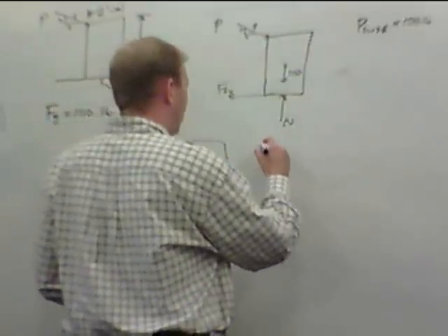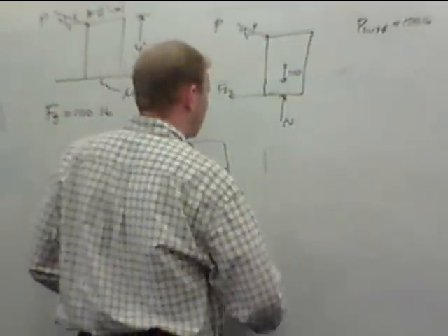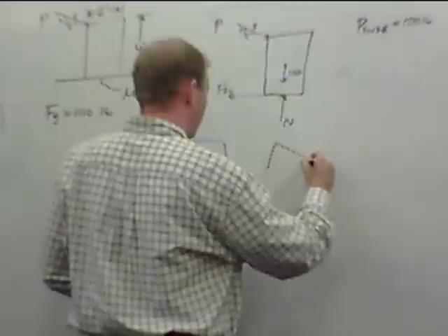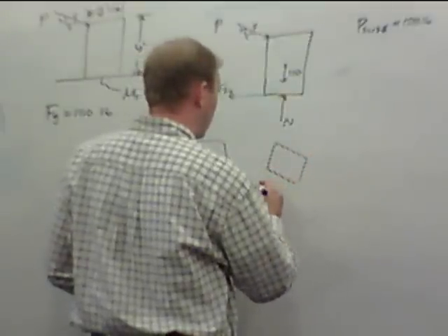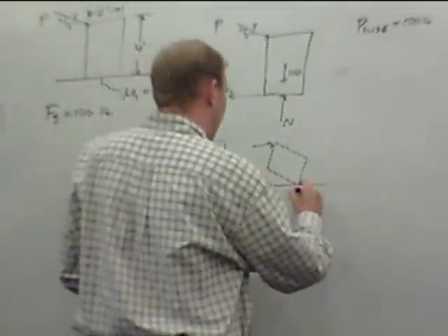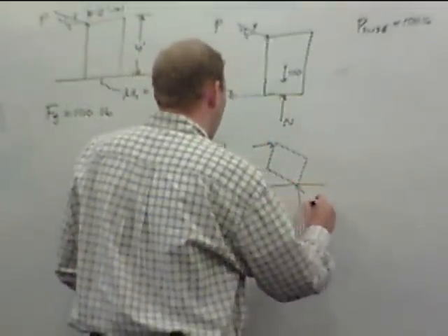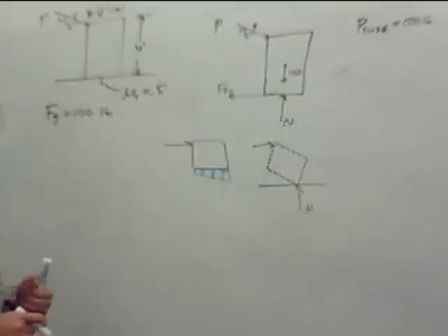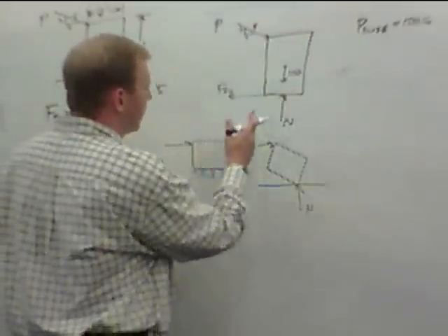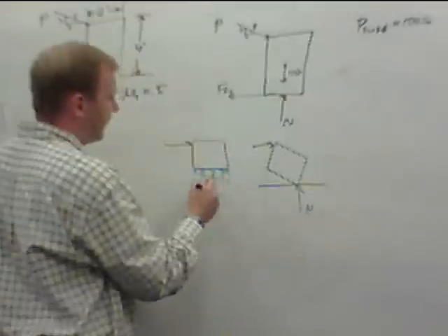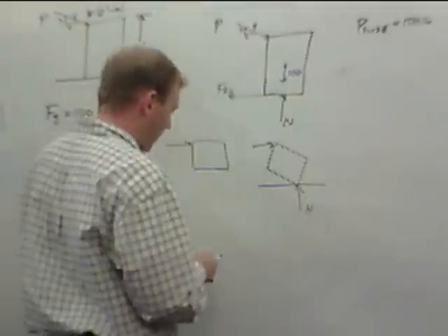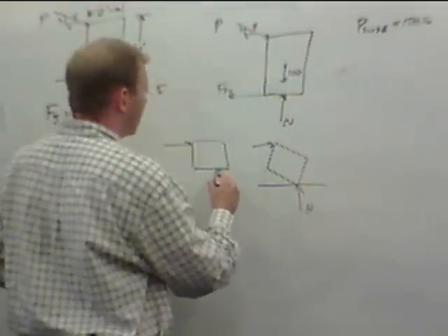Am I drawing this right? When it's actually tipping over, now the normal force is all applied on this one corner. As we start pushing and pushing, this normal force, if we simplify the distributed load into a single point force, is actually going to be shifted a little bit off to the right.